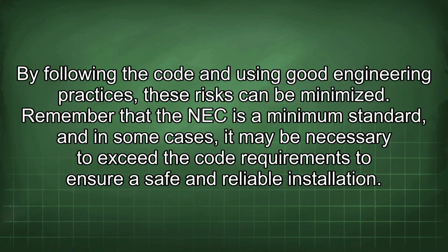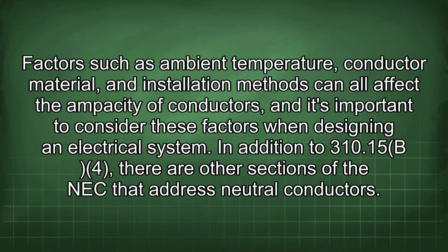Remember that the NEC is a minimum standard, and in some cases, it may be necessary to exceed the code requirements to ensure a safe and reliable installation. Factors such as ambient temperature, conductor material, and installation methods can all affect the ampacity of conductors, and it's important to consider these factors when designing an electrical system.